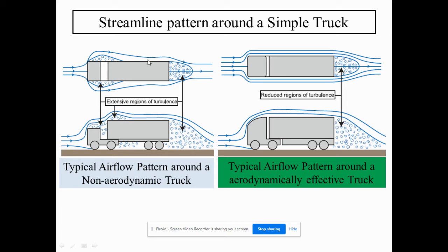All the rough edges and corners are almost straight edges. Whereas this is slightly aerodynamic, where there is a deflector. When the flow comes here, the flow gets separated. There is a lot of stagnation because the flow is coming and hitting here. This is from the side view. This is from the top view, and you can see the flow getting separated from here and going ahead, and there's a flow separation. And here you can see strong vortices.